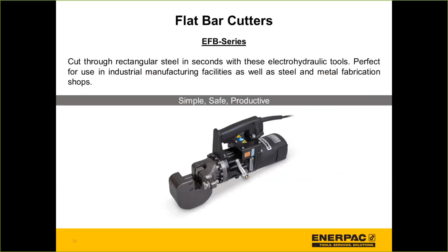Flat bar cutters. If you look at the flat bar cutters, you might be reminded a little bit of the bar cutters that are used for cutting rebar, because the tool looks and acts very similar to that tool. However, what's different about this tool, if you look at it, you'll notice that the head is shaped differently. It's shaped that way to accommodate, instead of round bar or rebar, flat or rectangular bar.